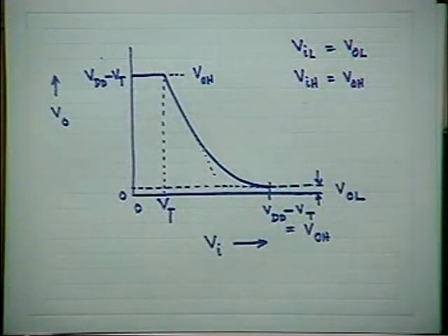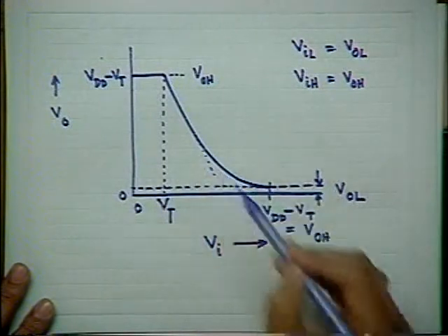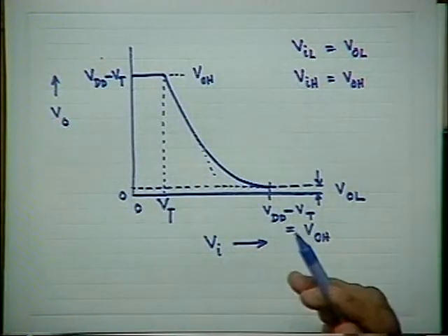Am I correct? And we have found that in the saturation region, the output-input relationship is linear with a negative slope. And the slope of this is simply equal to minus root over beta R. Higher is the beta R, steeper will be the slope.